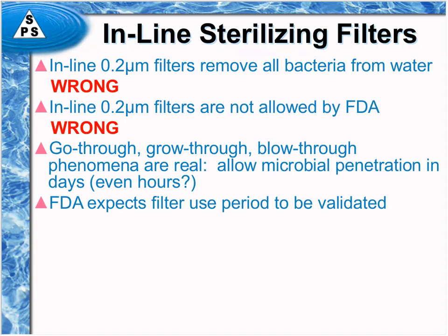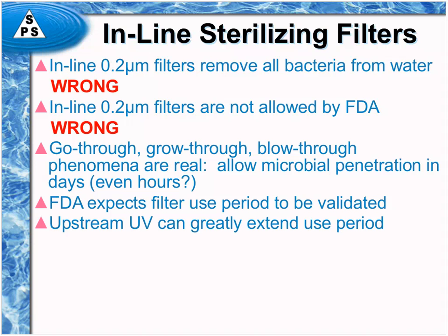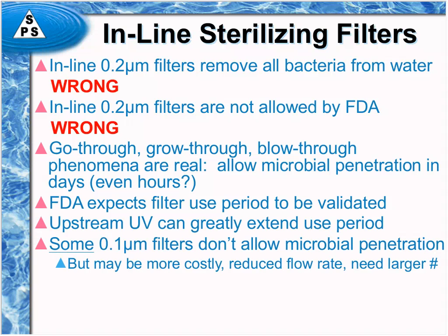It may be only a week or two, and it's not uncommon to see filters that have been in service for perhaps years because they haven't reached some magic delta P that would trigger a filter replacement. If you were to put a UV sanitizer upstream of the filter, you could greatly extend that use period to perhaps half a year or even a year, because the only organisms landing on the filter would have already been killed by the UV. There are some 0.1 micron filters that will not allow microbial penetration.